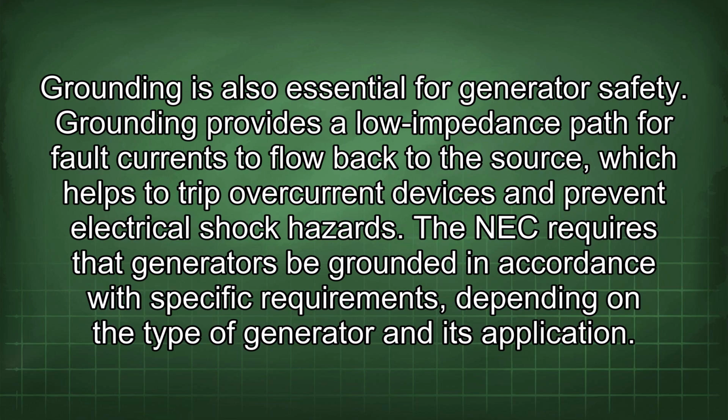Grounding is also essential for generator safety. Grounding provides a low impedance path for fault currents to flow back to the source, which helps to trip overcurrent devices and prevent electrical shock hazards. The NEC requires that generators be grounded in accordance with specific requirements, depending on the type of generator and its application.